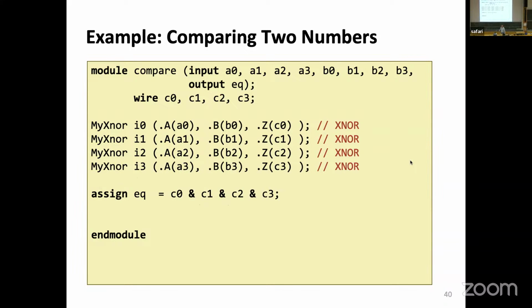Now we are getting a little bit better. Why do I write it in multiple lines? I can just do C0, C1, C2, C3. I save 2 lines. And now you say, but if this was a bus, I could do it in one go. And yes, because there was this cheat code, the AND C. But for the AND C to work, I need these guys to be in one bus. So I define them as the wires C0, C1, C2, C3. My secretive goal is to AND all of these together.